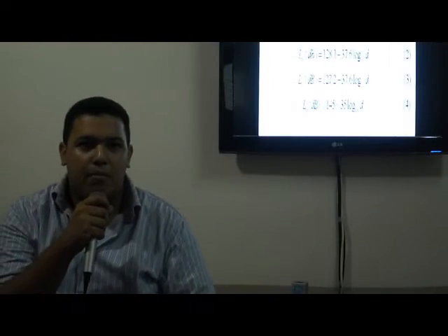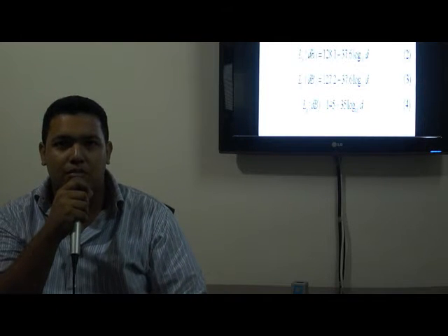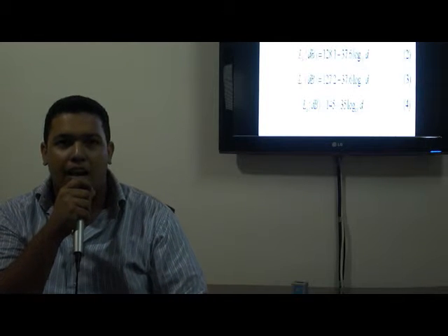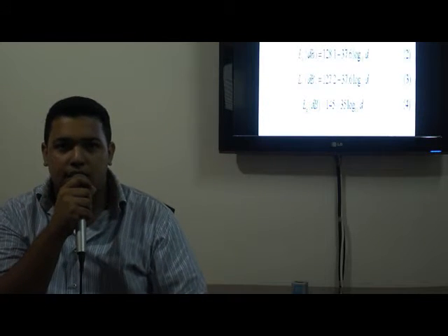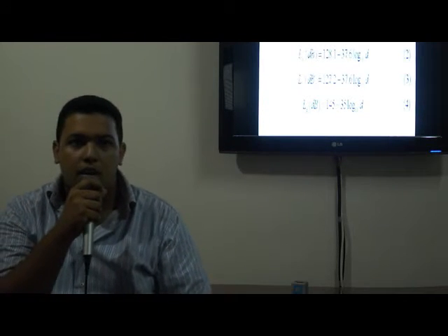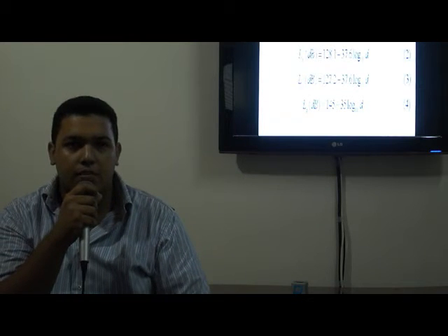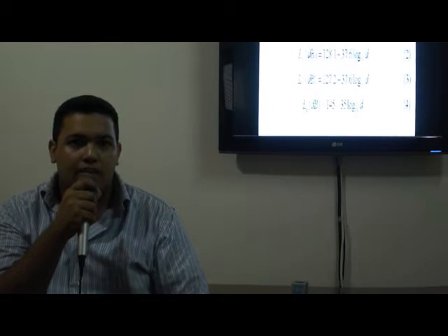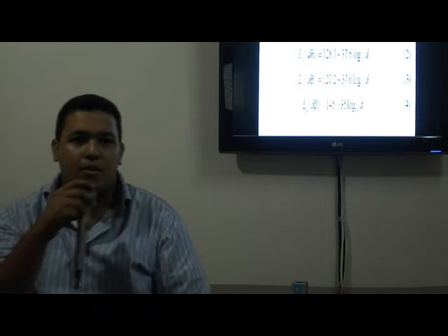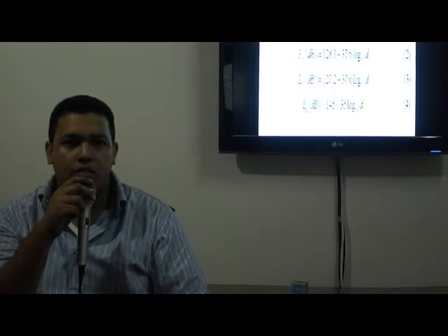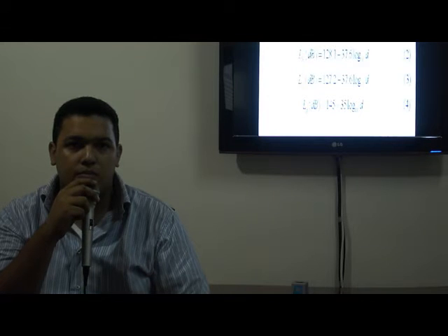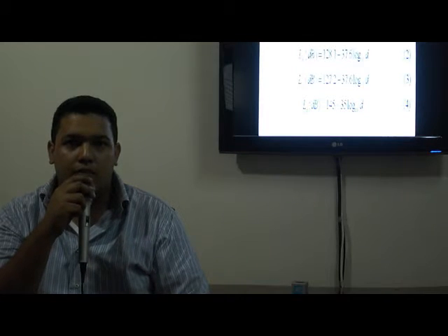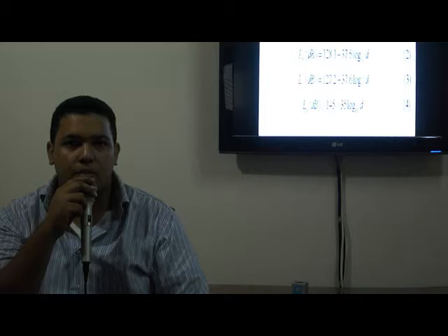Studies have demonstrated the importance of proper shadowing models to carry out investigation on RRM. In fact, the shadow effect results in additional signal attenuation due to the obstacles in the path between the transmitter and receiver. Measurements have shown that the loss due to shadowing can be modeled as a random process with a normal distribution of mean 0 dB and a standard deviation between 4 and 12 dBs depending on propagation environment.